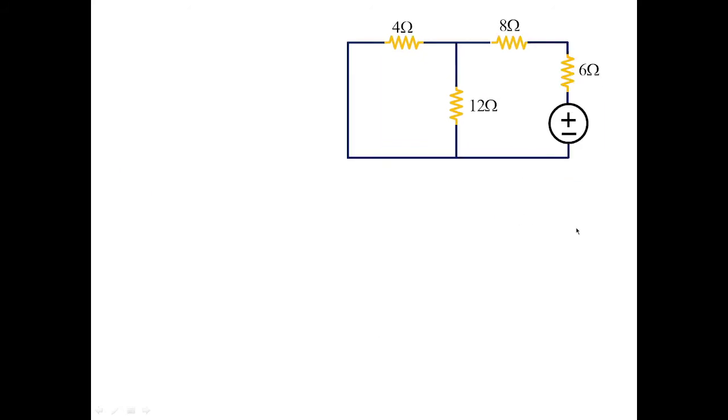I have taken the 15 volts voltage source and I'm going to place it over here, and find out the response from where it was initiated. Initiated means it has been removed from the first point where it was given as the excitation. So we are placing the 15 volts in the load where we calculated, and finding out the response in the place where we previously had the 15 volts.